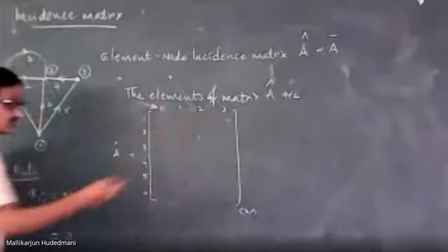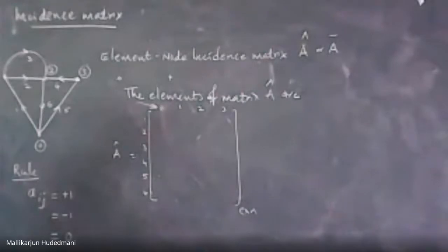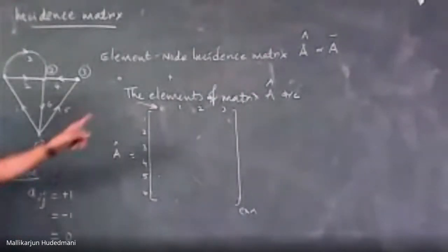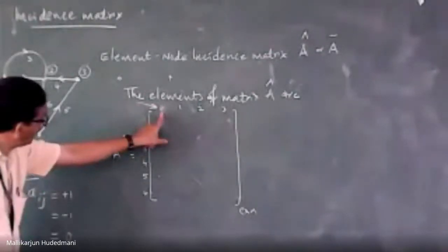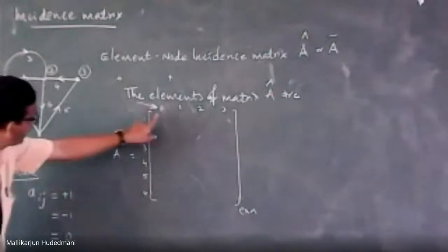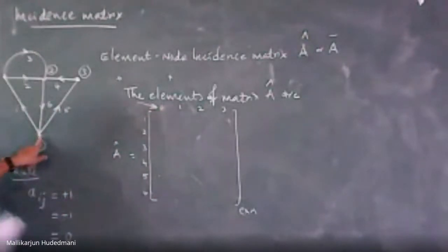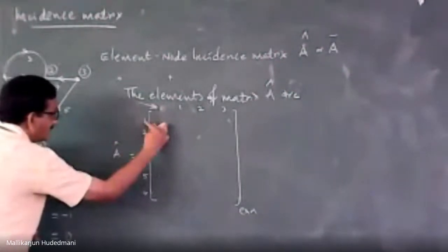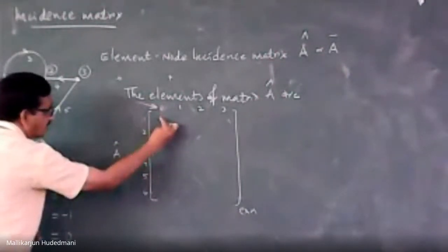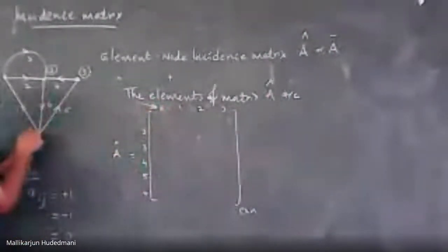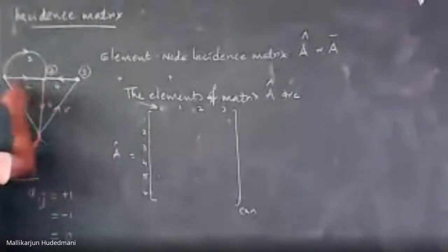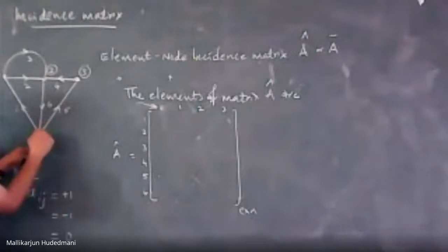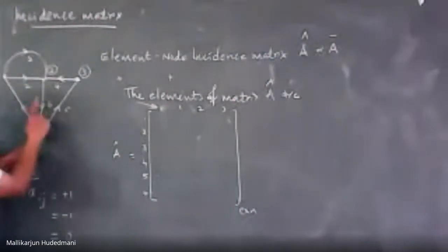Likewise, each bus, one at a time, you have to observe, apply the rule, and incorporate the representation. How to do it? Suppose I want to fill the entries of this. What is the meaning of this? At bus 0, I stand and observe whether element number 1 is incident to this, whether it has a connection or not. I should establish it. At this 0, element 1 is going out. Yes, there is a physical connection. Then element 2 is in no way connected here. It is not incident, not at all connected. Hence, it is not connected to this 0.